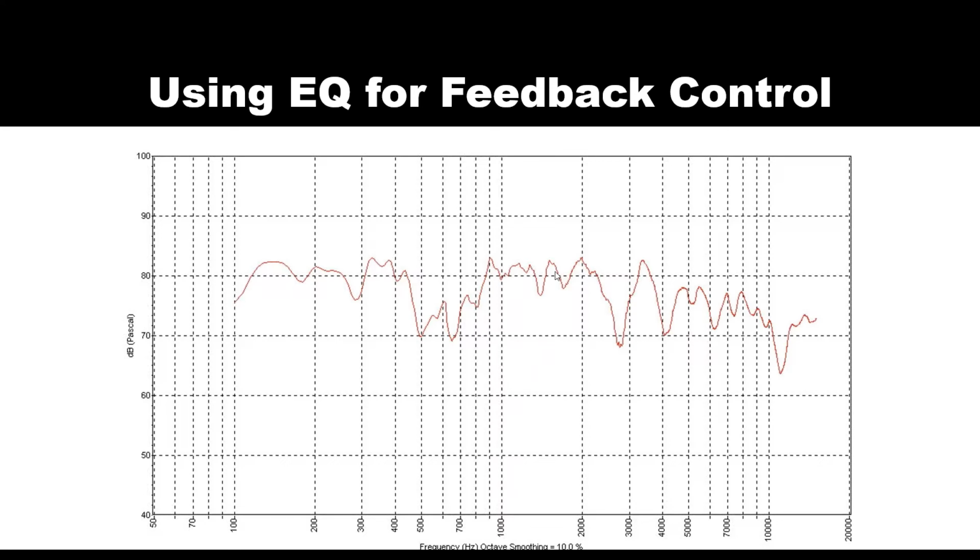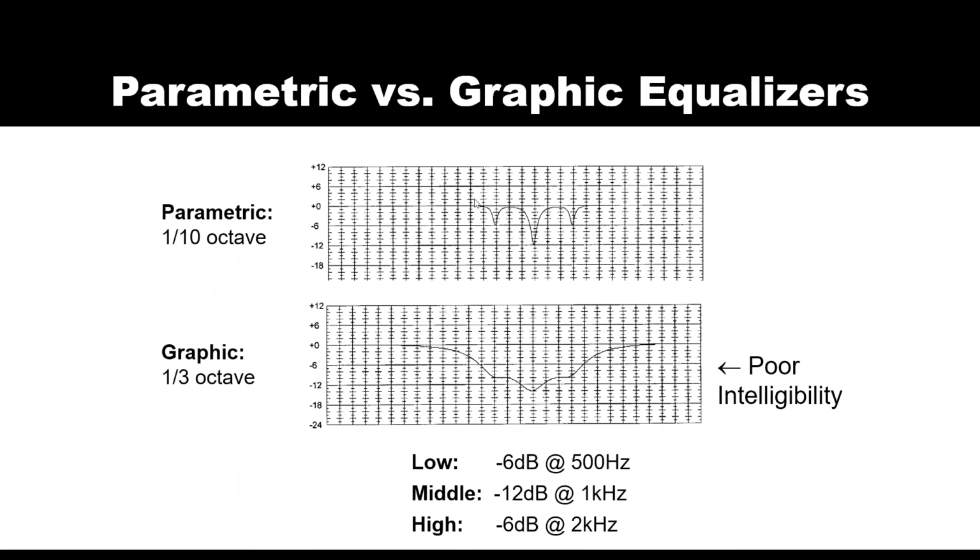And those are the frequencies that, as you keep bringing the level of your microphones up, are more likely to feedback first. So if you use equalization to reduce the sound system's output at these different frequencies and, to the extent that you can, flatten out the frequency response of your sound system, that is going to minimize feedback. The most common tool for this tends to be the graphic equalizer, what is known as the 1/3 octave graphic equalizer, which is often a 31-band EQ.